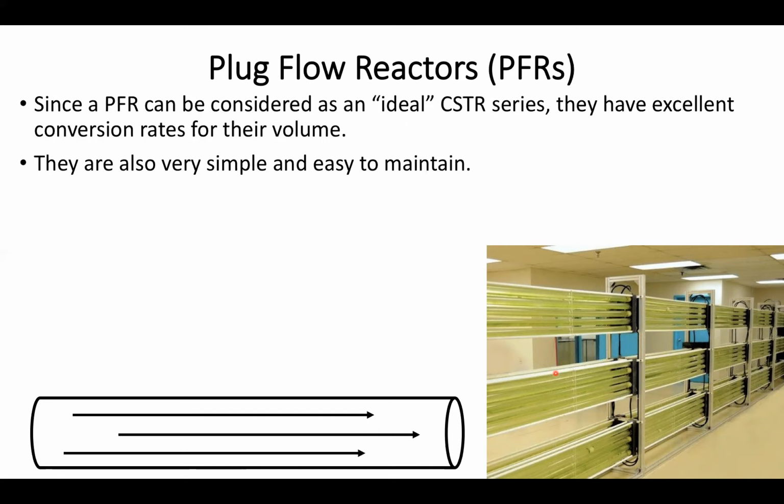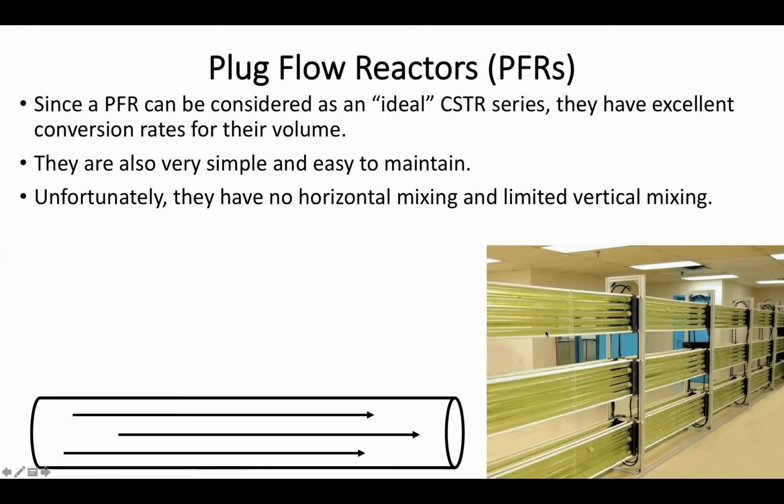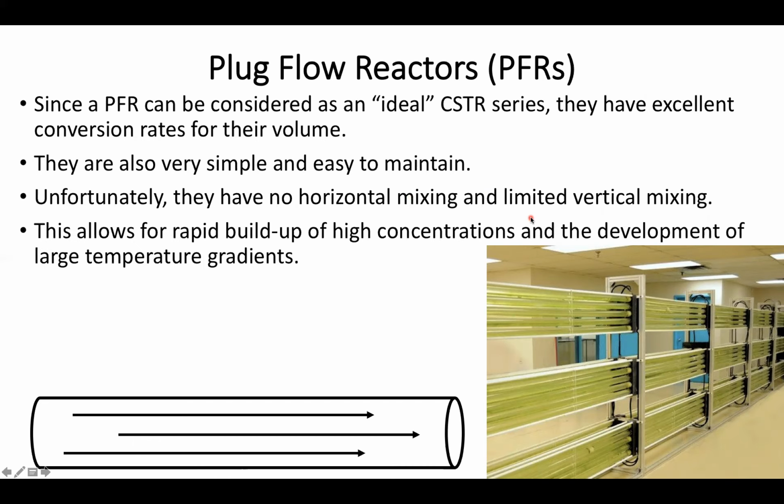However, you do often need fairly good pumps, and they have some problems with heterogeneity, because it turns out they're going to have absolutely no horizontal mixing, and the vertical mixing tends to also be very limited. However, it's not uncommon to put baffles into your PFR that help fight this sort of ill-mixed behavior. But one of the biggest problems is that because of this ill mixing, you can end up with some rather unfortunate high concentrations of products or reactants, which can occasionally result in the formation of deposits and degradation of the reactor itself.